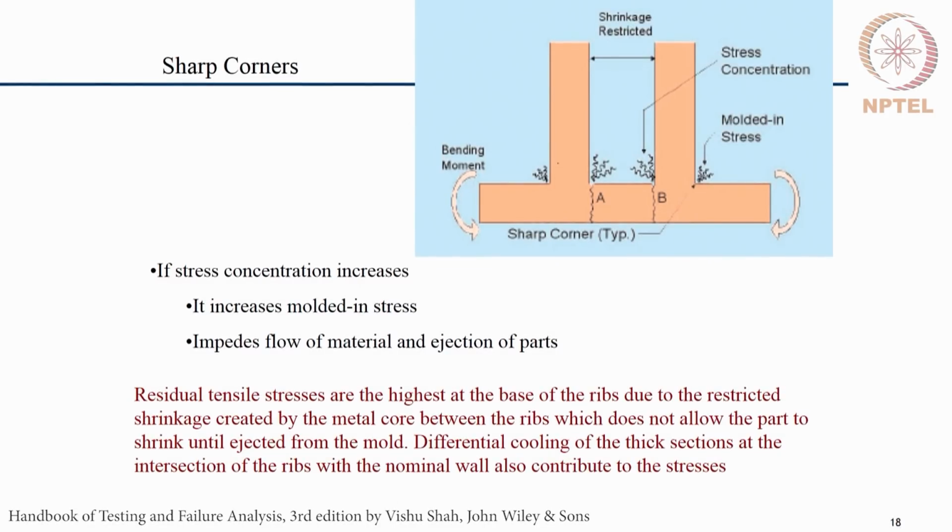First thing is to avoid sharp corners or provide sufficient radius so that the stress concentrations can be minimized. Wherever such stress concentration happens, failure will happen. The cracks can initiate at these points, and the part can fail.